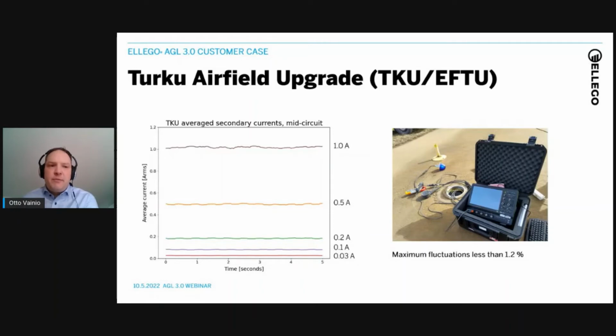Here we have a measurement from the midfield. So this is as far as practically possible from the CCR in the middle of the series circuit. The nominal power for this circuit. So when we did the retrofit installation, that will actually show up better in the next slide, actually. So the 1 amp is the current that's normally run in this circuit, and that more or less matches the neighboring halogen circuits. I would say that the LED is slightly brighter than the halogens with their nominal power in this case, but I'm perhaps a little bit biased.